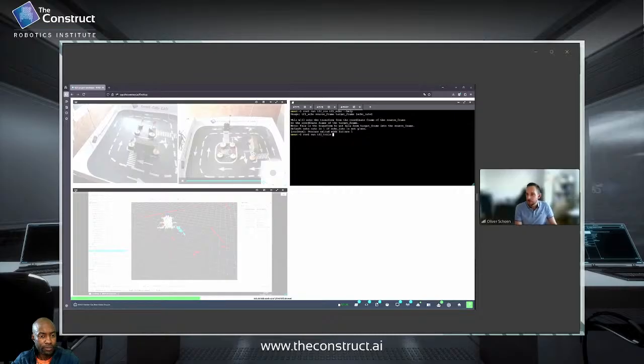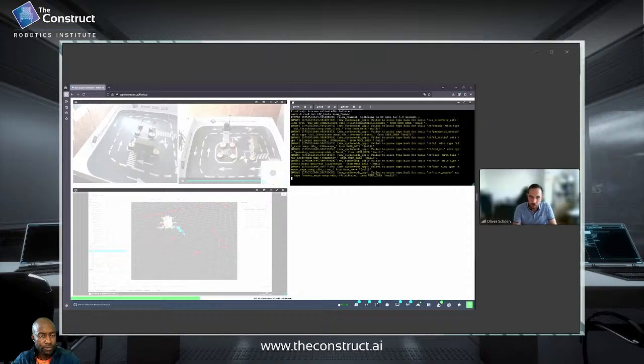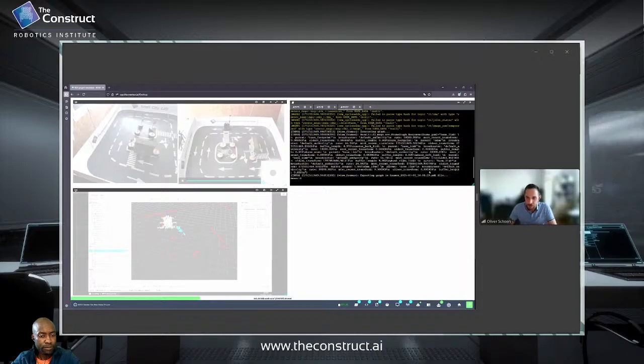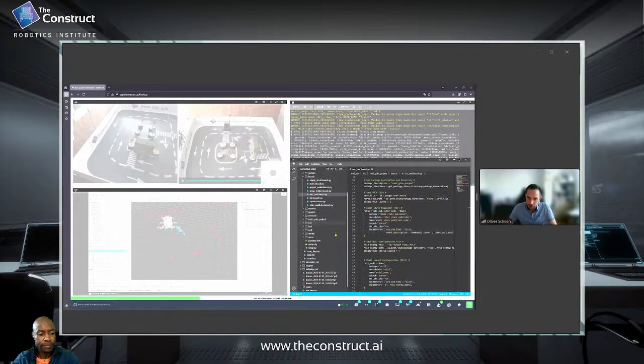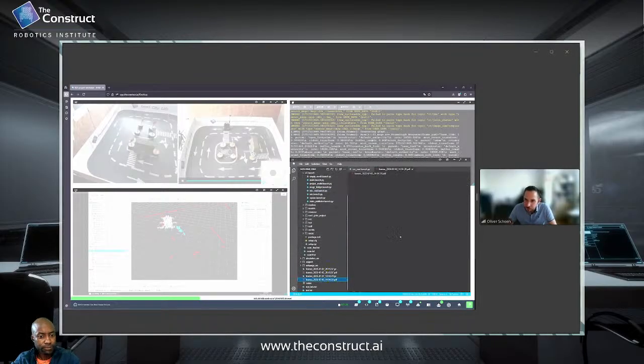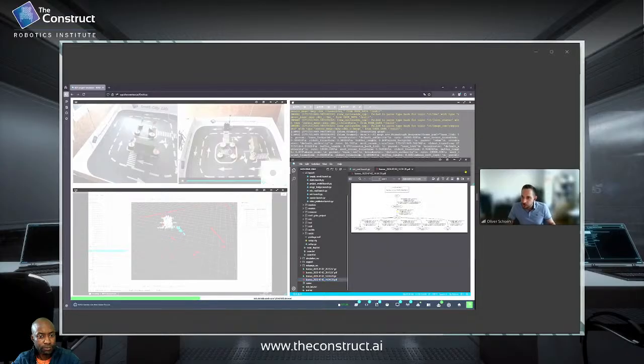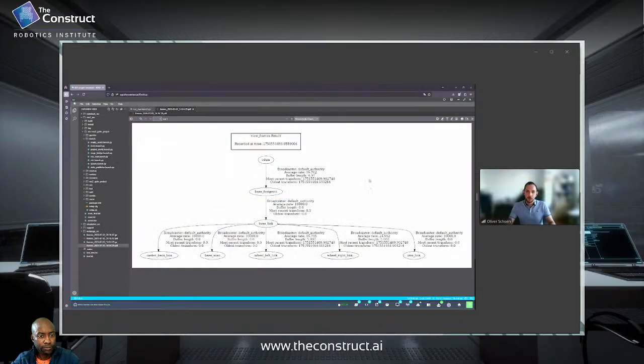Tools. And then it's called the view frames. The view frames is basically recording all the transform data that is published, and then saving it in a PDF file and providing kind of a tree. So if we quickly go into our files here and open it, then this is the PDF file, and you can see the whole kind of frames and the transforms from which frame to which, so to say. So it's not the actual transform information, like how it is transformed, but just how it's connected.